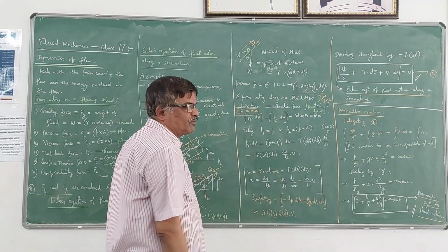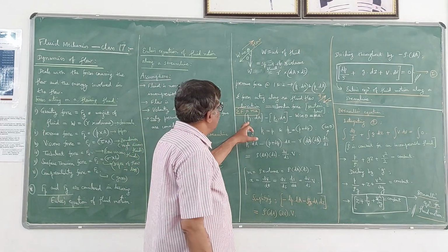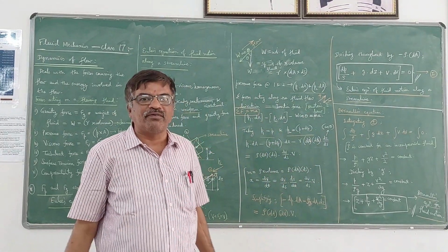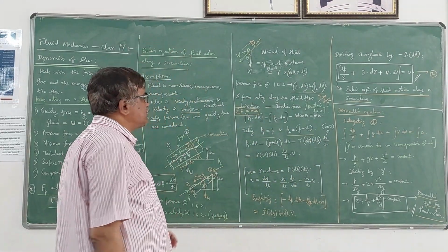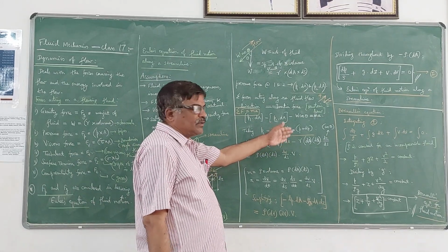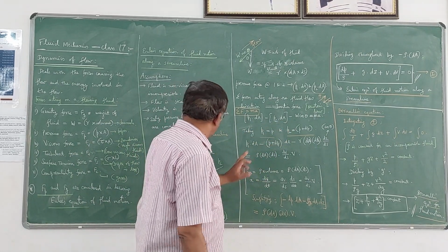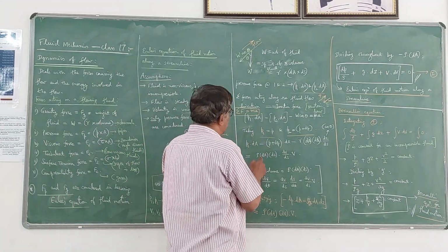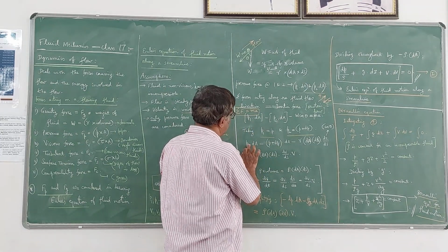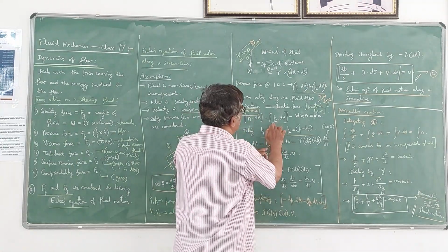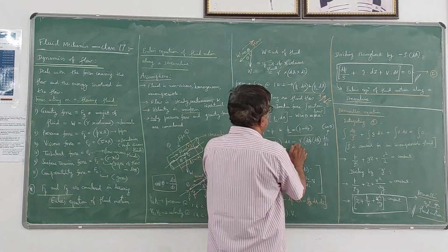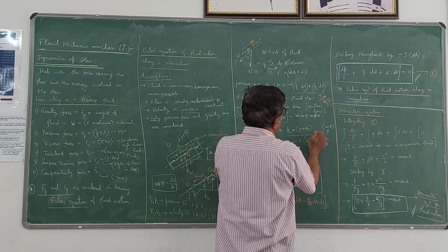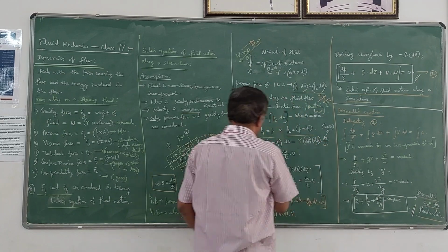Now we have to substitute for all these things. I will take P1 as P, and P2 as P plus dP, because the pressures are different. There is a change in pressure, that is why flow is occurring. And you know that cos theta is dz by ds. Now if you substitute those things here, it becomes P into dA minus (P plus dP) into dA minus W, where W is gamma into dA into ds into cos theta, which is dz by ds, is equal to...